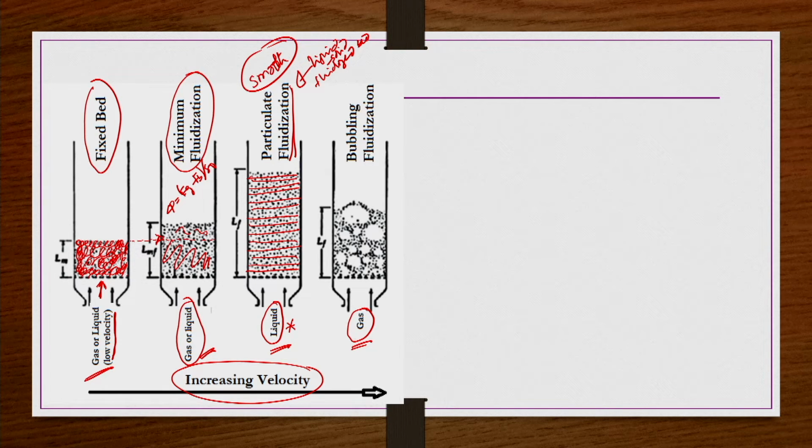But now if you have a gas-solid fluidized bed, and the superficial velocity of the gas is sufficiently larger than the minimum fluidization velocity, we can have a bubbling fluidized bed. That means some voids or bubbles are forming here, like that I am arrowing, and these voids or bubbles are almost free of particles. Within these voids or bubbles there are no particles in general, or very few particles. Such voids or bubbles are formed.